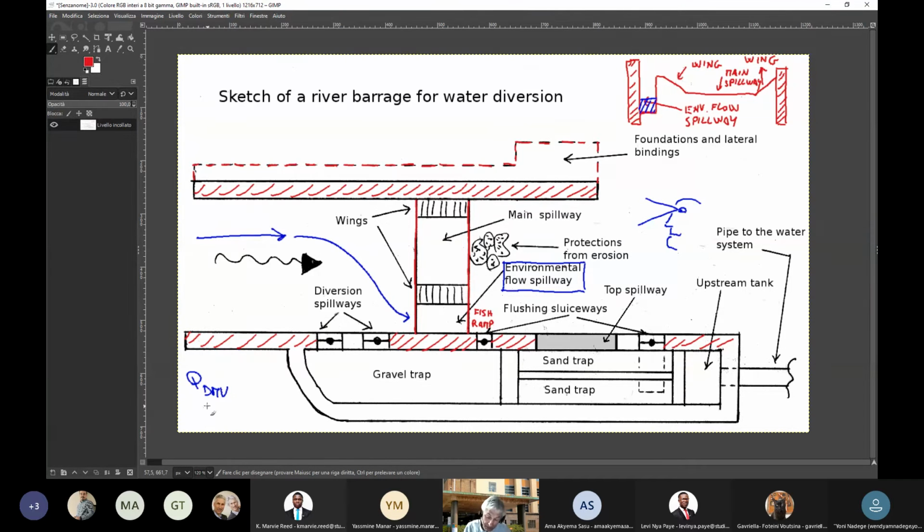That's true, but if the flood is very large, the effect of the wings in terms of additional elevation upstream is not very significant. And if the flood is not very large, the wings are effective in keeping the main flow, let's say the main velocity, far from the hill slopes. We don't want water flowing with very high velocity against the sidewalls, against the hill slopes, okay? So we usually create the wings.